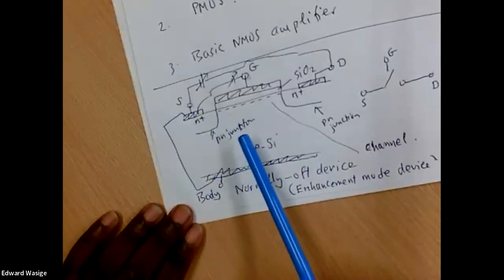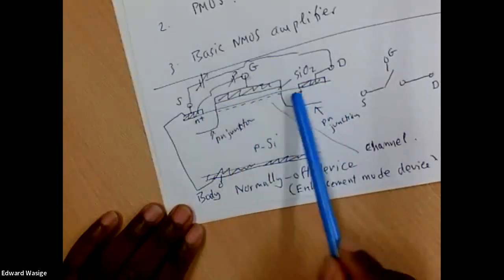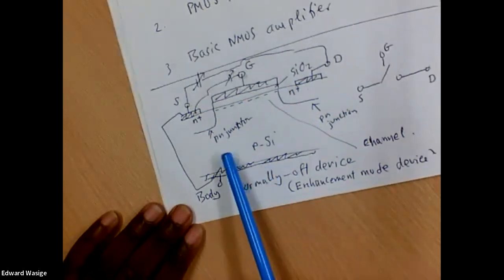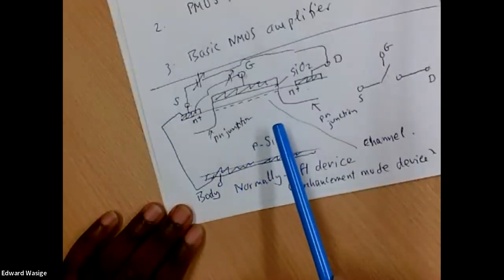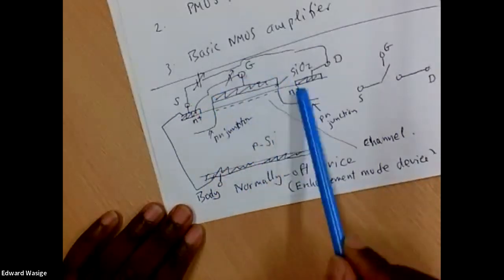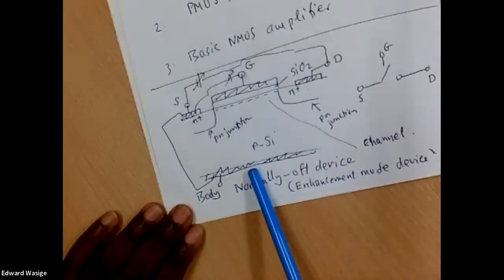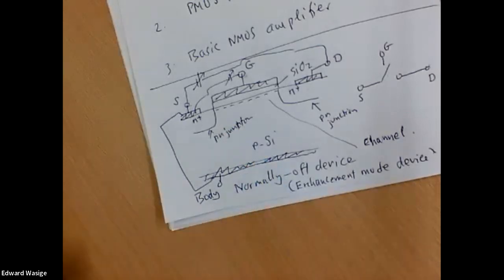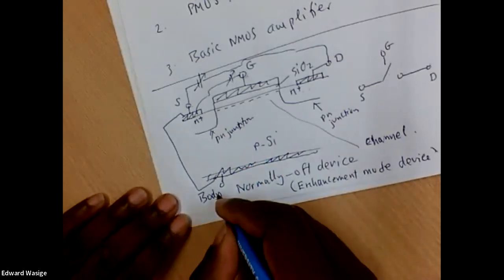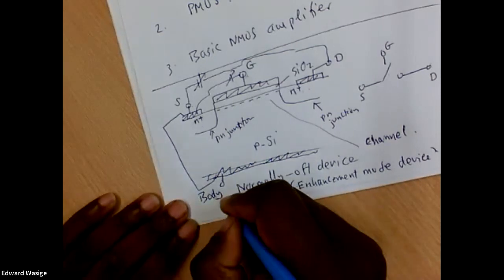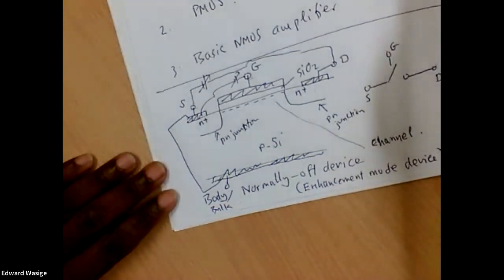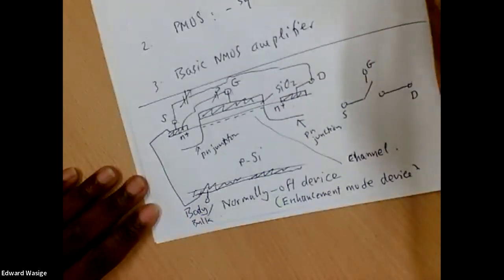So that means we don't have transistor current where you don't want it. You want it to flow in this channel region. You don't want it to come outside of the transistor. And by connecting it like this, we ensure that the transistor is nicely isolated here. We don't have currents that flow towards the bulk of the transistor. It's called the body contact, or sometimes also called the bulk contact. So I'll summarize this on the next page.